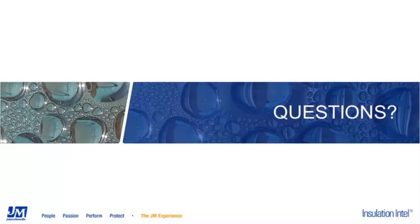So it's very important. We've talked throughout the presentation that a sealed system with proper vapor retarder integrity is critical to preventing moisture drive into the insulation. So very important. If Jim wants to elaborate on that any more, I'll let him speak to it.